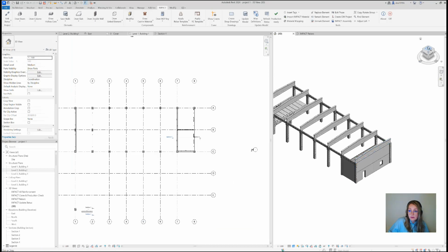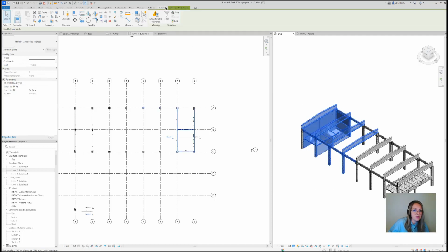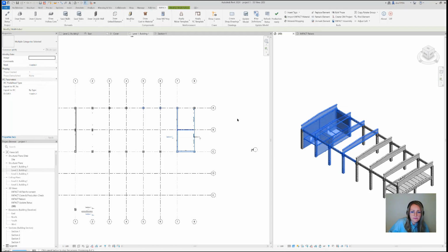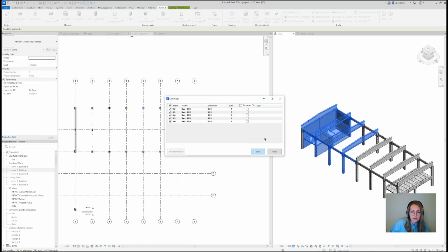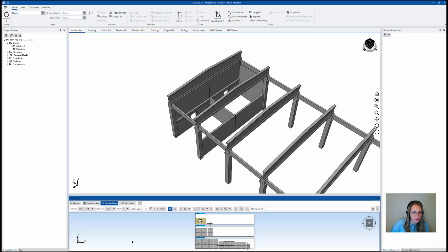We missed the slabs. We missed saving the slabs. Now when we're saving, it's basically the same procedure. Instead of selecting one by one, I'll do it the easy way and say save slabs. Impact is scanning, finding out which one we define as the product slab, and slabs are being saved. Once we save the slabs, they become an assembly, and we are going into the project manager.